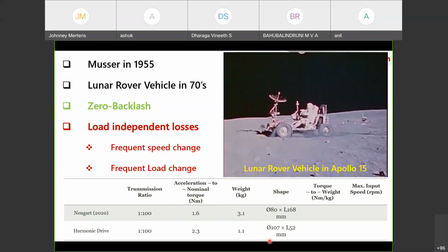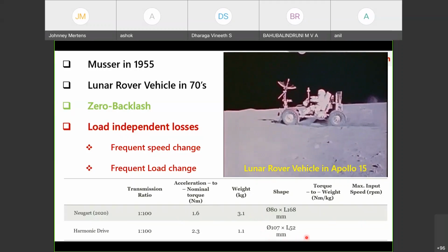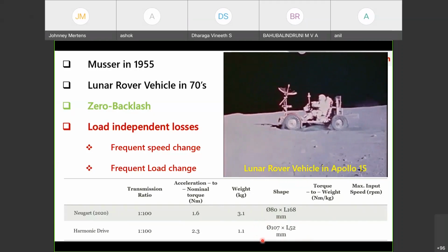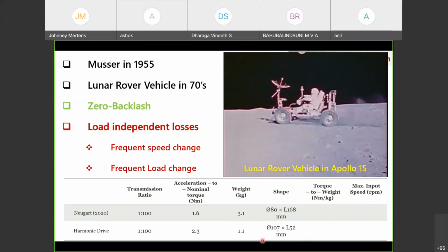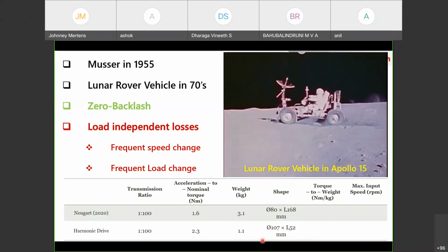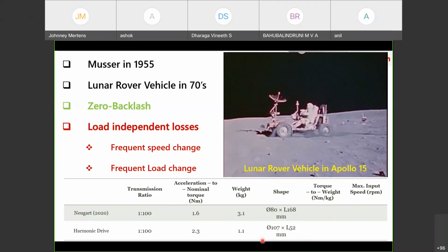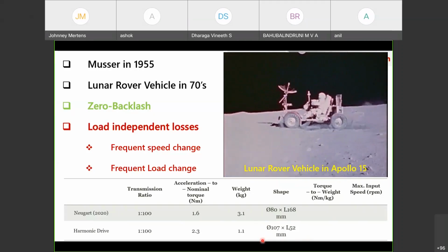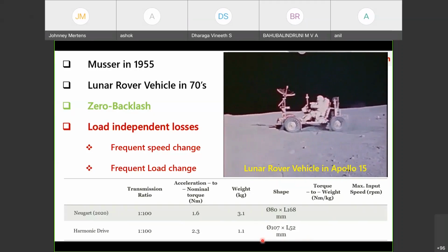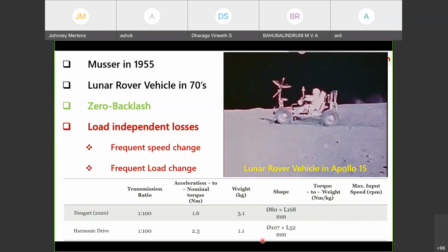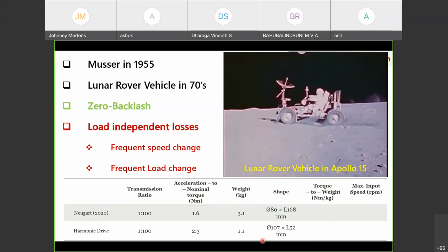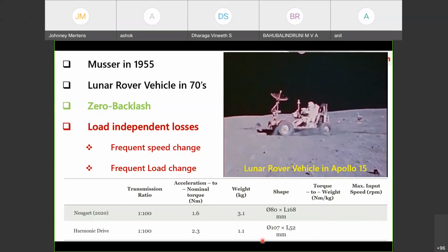But whereas you can see this diameter is 107, but the length is 52. So more than half length reduction is happening due to this harmonic drive system. Why is it reduced? For example, if you use the planetary gear system, you are supposed to give some thickness to the planetary gears. Instead of giving that thickness, in this harmonic drive, this thickness is reduced.